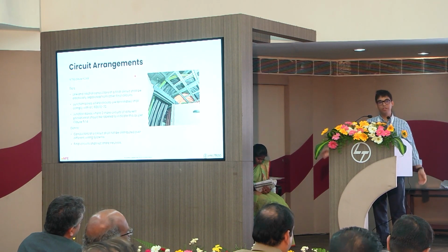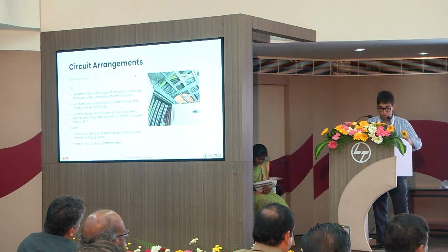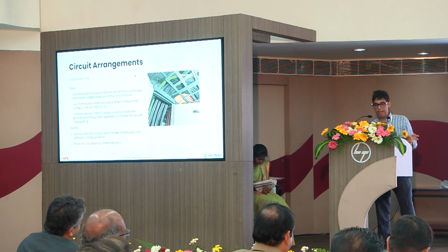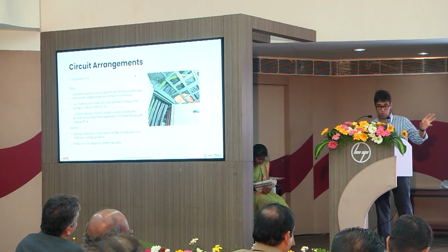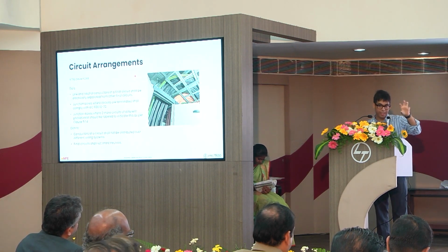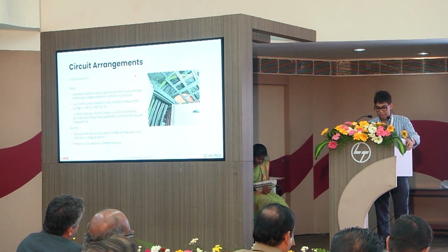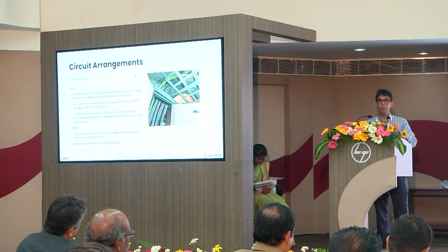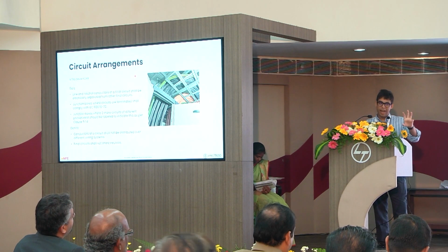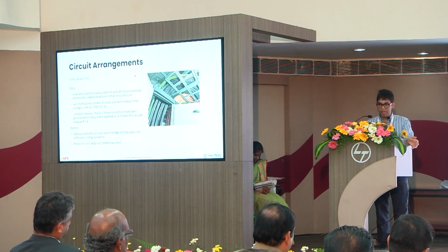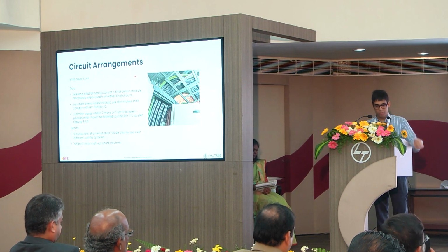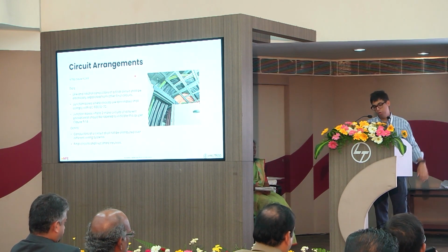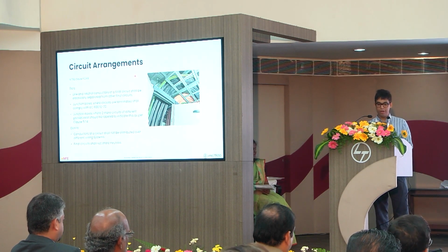Now, junction boxes, very often they just tape the connectors together and leave it in the trunking. No. A junction box has to comply with the relevant IEC standard 60670, and part 22 is the requirement for connecting assemblies, because the standard covers a lot of other enclosures. Then, if a junction box has 2 or more circuits of different phases, there should be no possibility of confusion. This is a should, by the way, it's a recommendation from my side. Because at the end of the day, from a maintainability point of view, which is a fundamental principle of 732 and SP30, this needs to be considered. So it has to be labeled as per, and 514 goes into labeling. Please do not distribute the conductors of different systems.